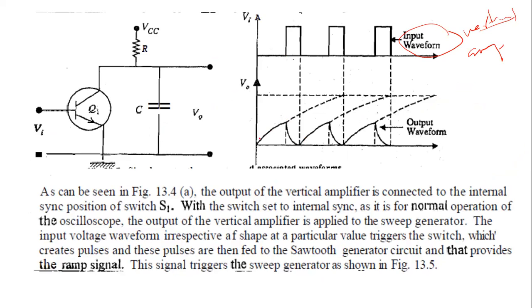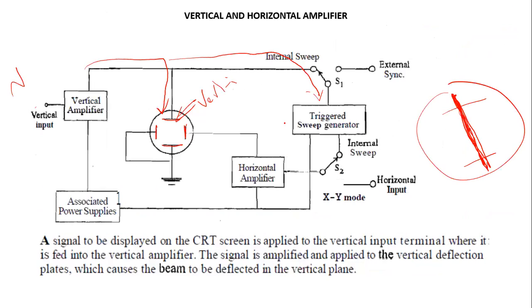So when you supply a sawtooth wave, for example, let's say this is the time axis. Between this and this, your voltage is increasing almost linearly. And then in this sawtooth generator it drops down. And then the voltage is increasing almost linearly in this interval once it converts into a sawtooth. So that kind of linearly increasing voltage is given to this horizontal amplifier.